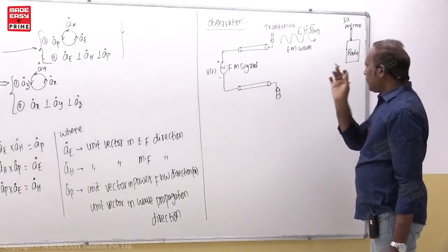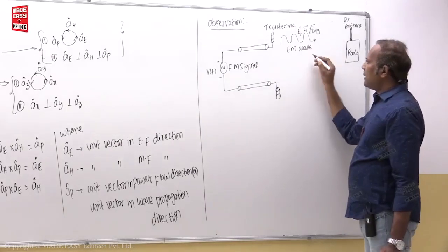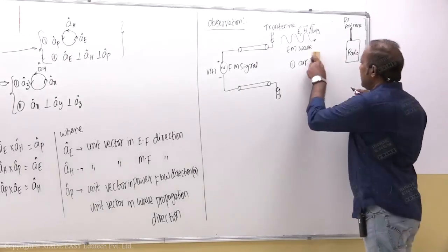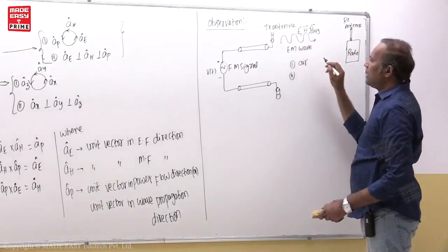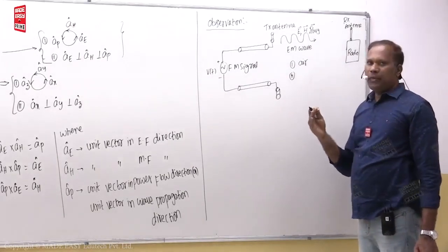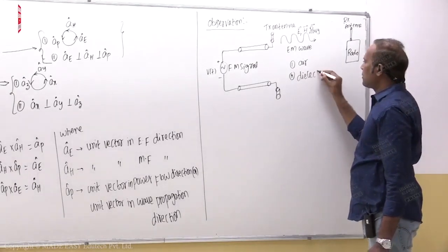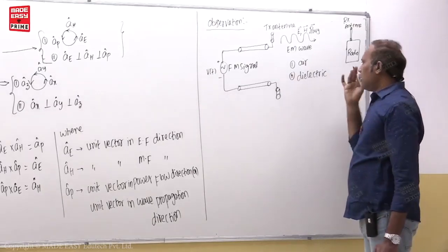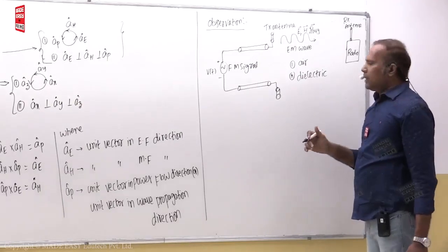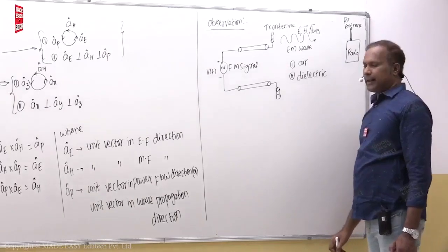Now whenever EM wave travels, it travels in air medium, or otherwise it is also called free space, and in between so many buildings come. Then that building wall is made up of cement, that is dielectric. So that EM wave travels in the dielectric medium also. So that dielectric has two types. In the dielectric sigma is 0, that is called lossless dielectric.